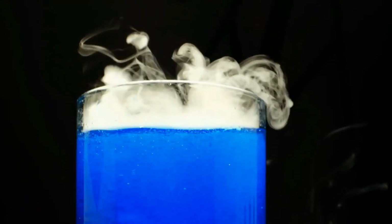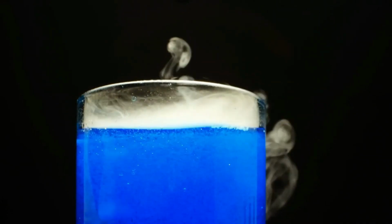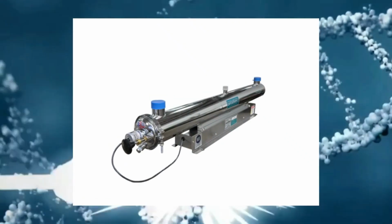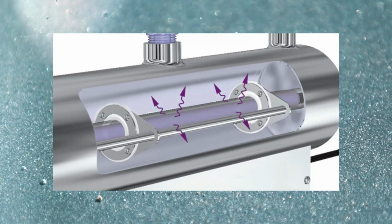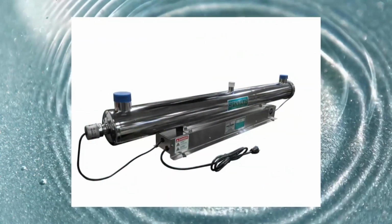Instantaneous. Unlike chemical methods that require time for the disinfectant to mix and react with the water, UV purification works almost instantaneously as the water flows through the UV chamber. Safety and simplicity. UV systems are straightforward to install and maintain, and they do not create handling or storage risks associated with chemical disinfectants. UV water purification exemplifies a clean, effective method of ensuring water safety.